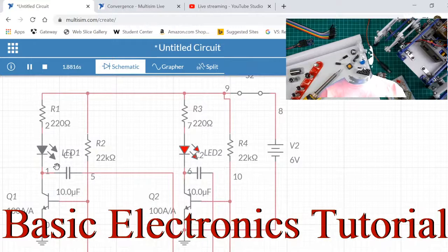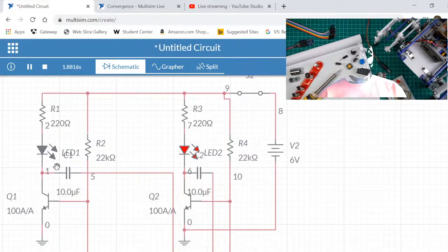Remember this circuit, we just built it a few minutes ago, where both of them were on basically at the same time, and none of them is controlling the other. But the moment we introduce this capacitor, the concept of time comes into place. T is a function of R and C, right? This is the on time and off time. So we're going to solder up the circuit later. Maybe in another video we're going to show how we solder this, but this is basically it.